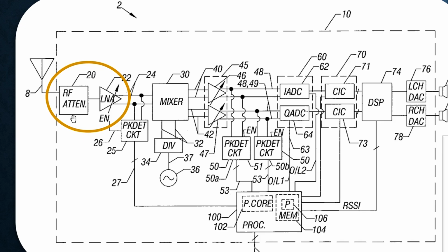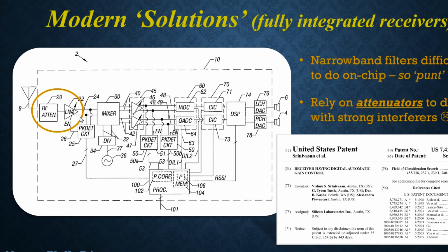That's a really, really bad idea when you're trying to get low-level signals. But it's needed to attenuate the high-level signals. So yeah, you can get rid of the intermods, but in the process, you just wreck the noise figure of the low noise amplifier. So these two guys together could have really bad noise figure.